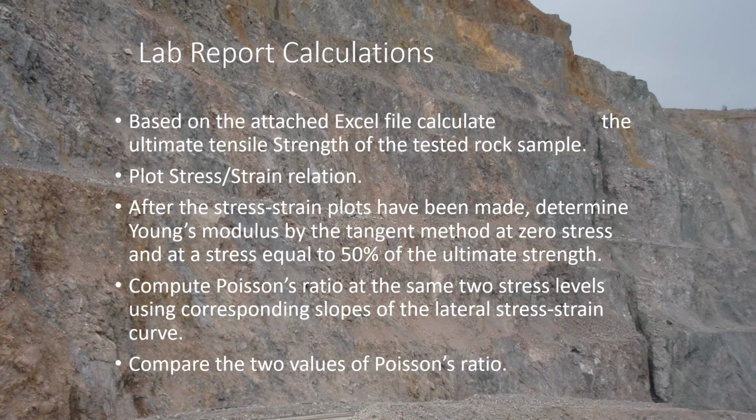So for your lab report calculations, use the attached Excel file with the collected data. And first of all, calculate the ultimate tensile strength of the tested rock sample, plot stress-strain, and then after the stress-strain plots have been made, determine Young's modulus by using the tangent method.